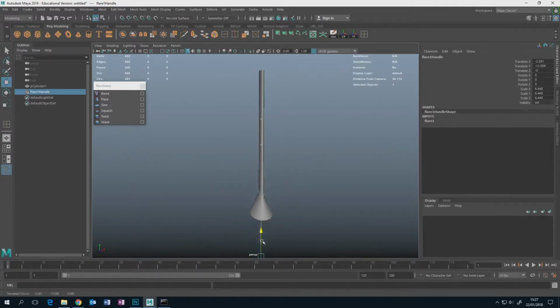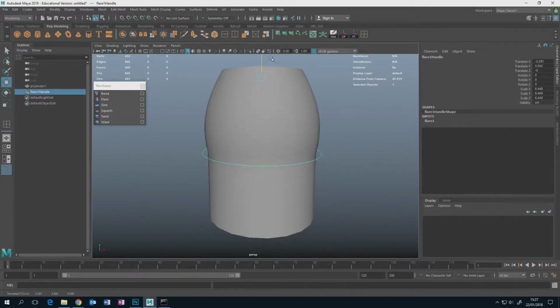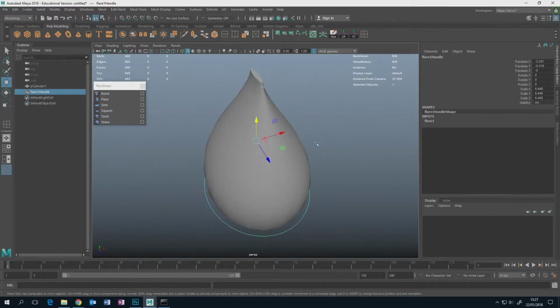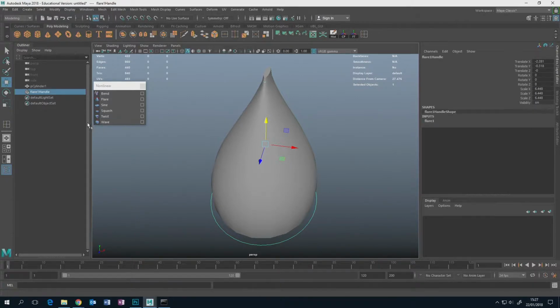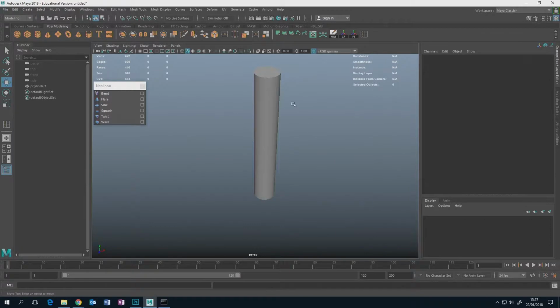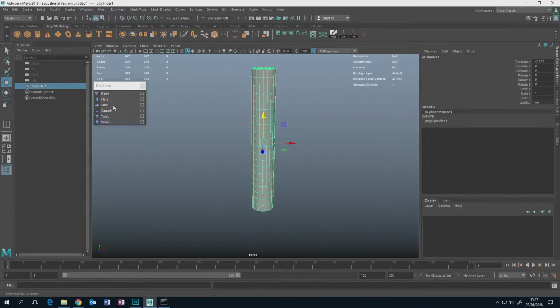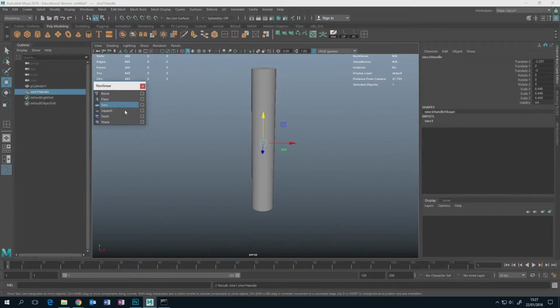So let's look at bend first. You click bend, and nothing happens to begin with, but it has created a new little object, this kind of line, and it's selected it as well, and it's called bend one handle. If I go to the behavior here in the attributes of bend, it can also be seen in the channel box. Just a matter of preference which one you prefer.